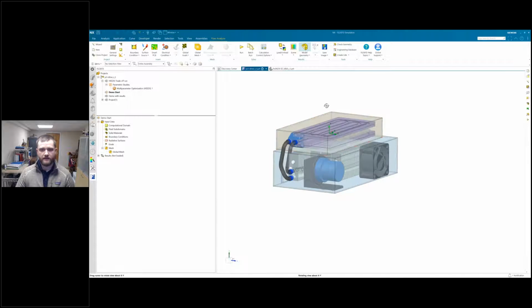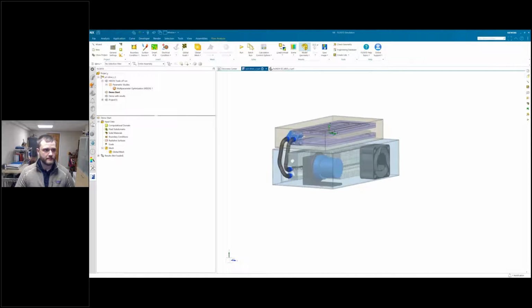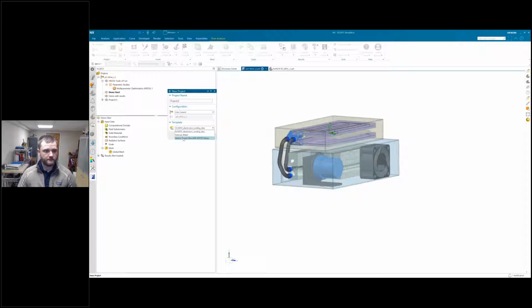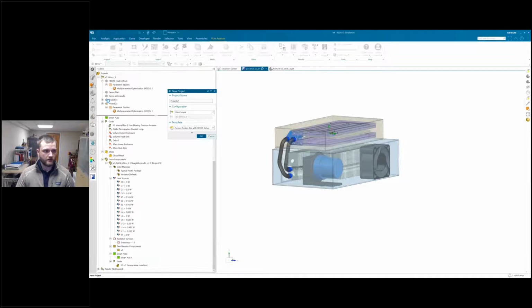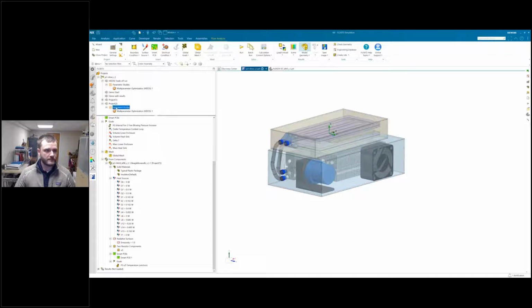So if I want to already have an analysis, and I'm doing maybe a lot of iterations on this, and I have a template that I can set up for it after I've done my first analysis, that's a really easy way to create these new analyses. And let's say I'm creating a new project, I can hit new, and I have the sensor fusion box with heat set up, where maybe I start off an analysis and then I'm doing a parametric study afterwards. Once I do this, my project is automatically created. So that's fairly straightforward, just creating a project like that.